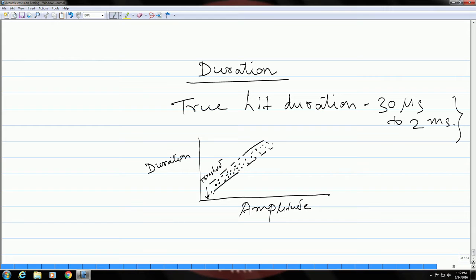You might also observe some discrete signals coming here and there. For example, you could have something above the band like that, or you may also see something which is below the band, like this. Since these are not falling within this particular band, this itself is indicative enough that although these are being picked up by the sensor, these are not really coming out from actual acoustic emission events related to defects and damage in a component.